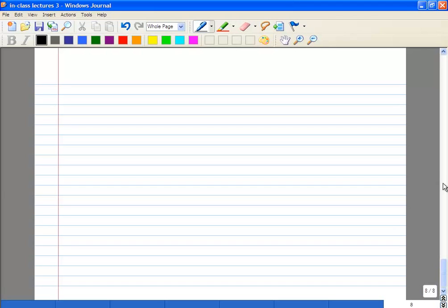Right now this is the SNR for the indirect switching noise. Of course the total SNR would be this thing. This is the SNR just for the indirect switching noise, because you want to take each noise source separately by itself, calculate the SNR, and find out what you want to do to maximize it. So that overall you'll know what to do.